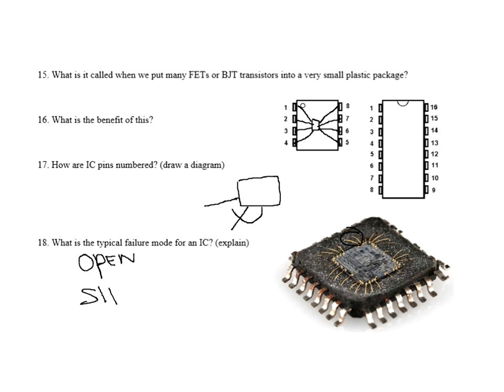So what are the two modes of failure for almost every integrated circuit? Generally, the tiny circuit chip inside is very, very durable. Usually the failure mode revolves around these wires in here. They can either burn open or they can burn open and then short by laying on top of each other.